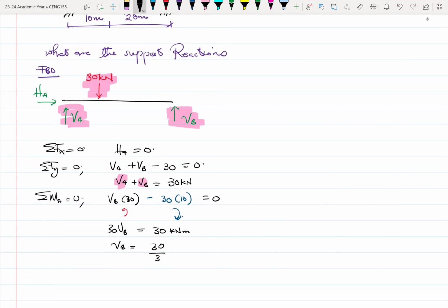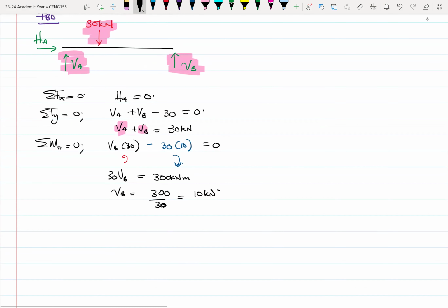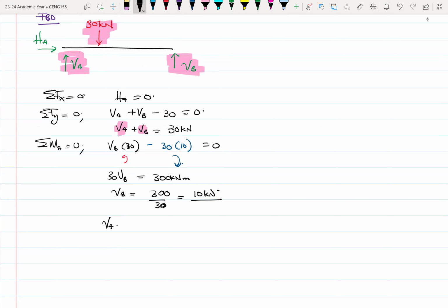Am I doing the right thing? Oh, 300, sorry. Today my brain is a bit slow. So that'll give me 10 kilonewtons. So VB is 10 kilonewtons, which means that our VA will be 30 minus 10, and that'll give us 20 kilonewtons. All right, great. So we all have our reactions.